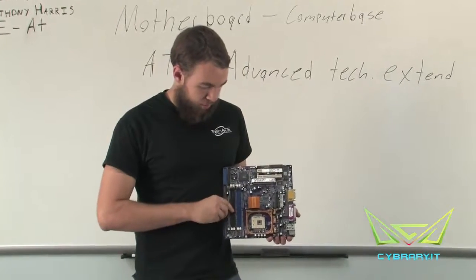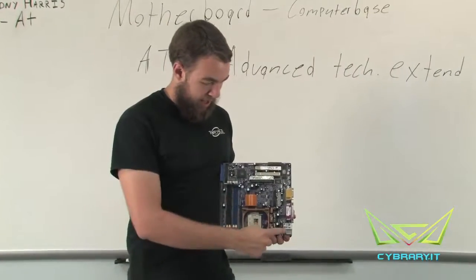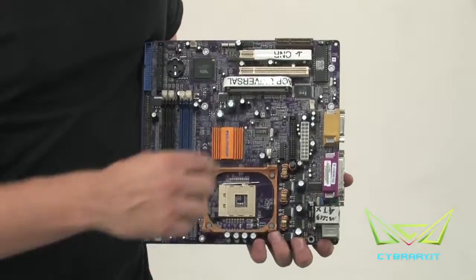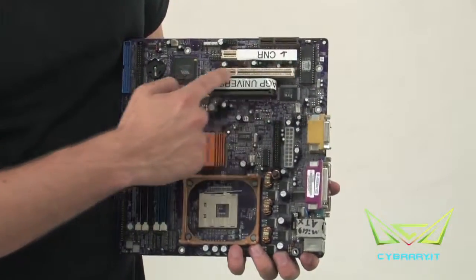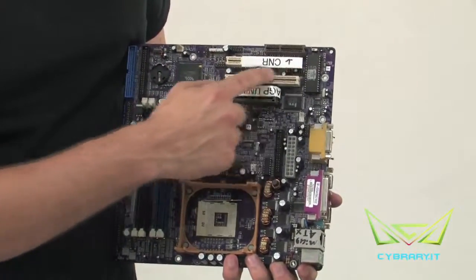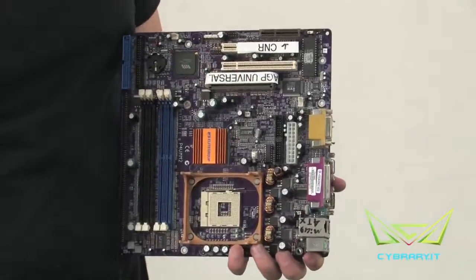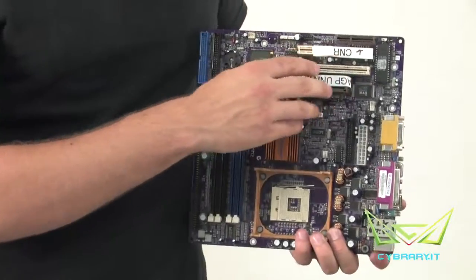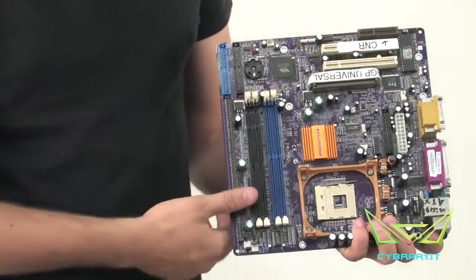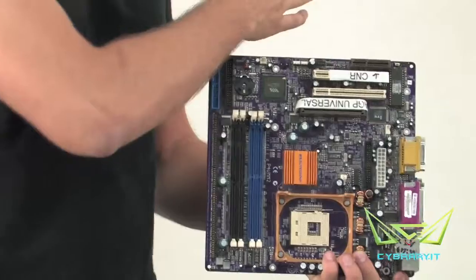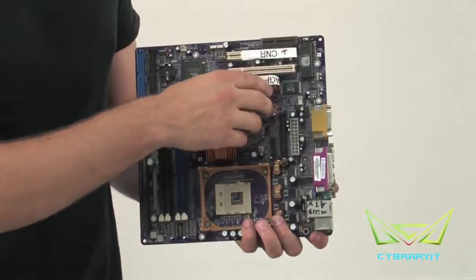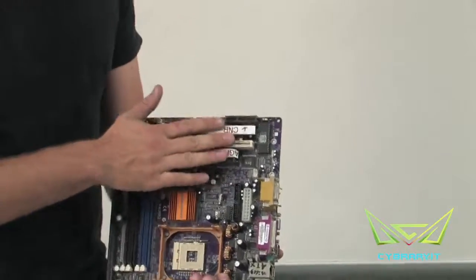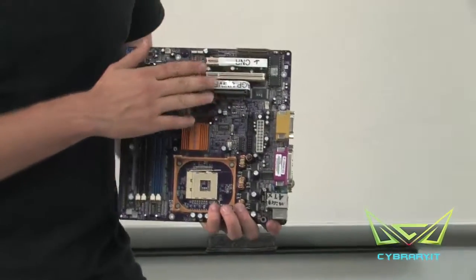On our ATX board, as well as our micro ATX board, we're going to have a rear input-output cluster. We're going to have expansion slots, which are parallel to the short side. We're going to have a left side case opening, so when we're looking at our computer, the computer is going to open from the left side. We'll have 7 expansion slots at the maximum. Now, of course we have less because this is a micro.